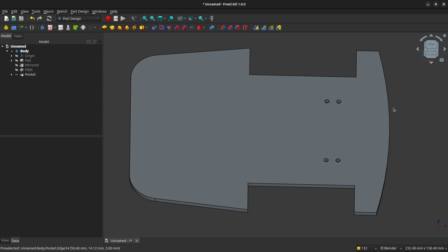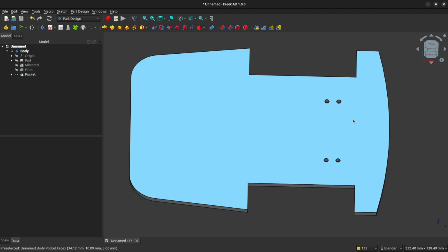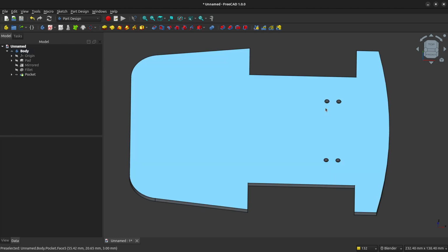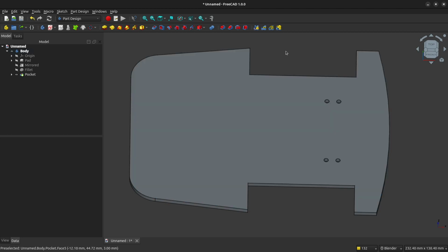Now we are using speed sensors to track the rotation of the TT motors in our robot, and the speed encoder discs that go on the end of these double axle motors extend down below the bottom of the base plate for SparkBot. So we've got to create a slot in the base so that these encoder wheels don't rub on the base.